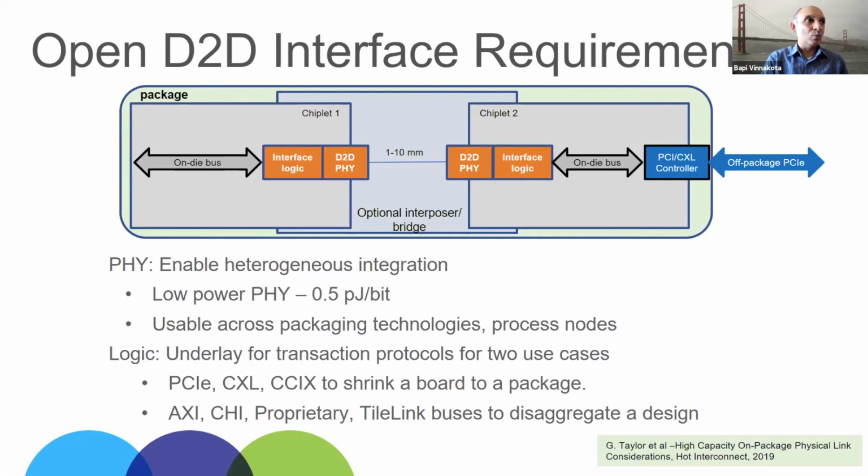So effectively, when you choose a die-to-die PHY, you're also choosing a packaging technology and the associated routing complexity. It comes as a package deal, right? When you buy an interface as soft IP, what you're really doing is buying the in-laws as well, effectively. You're buying a whole bunch of things at the same time.